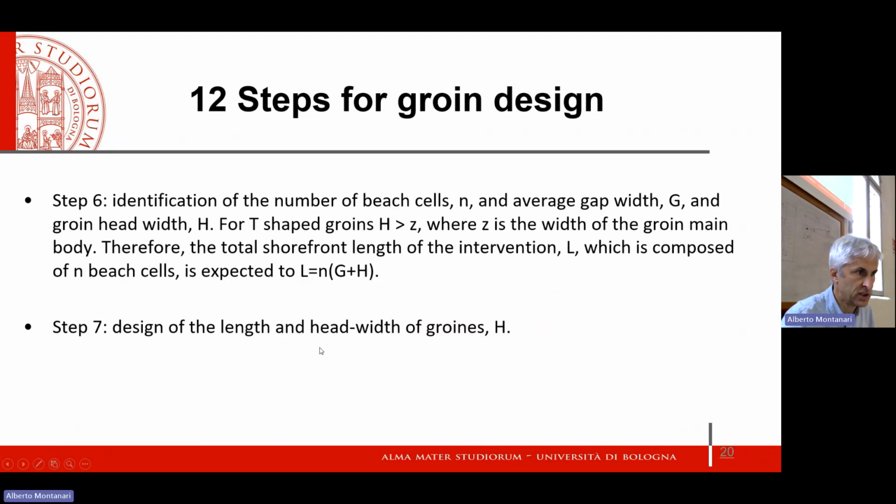Now, step 6, identification of the number of beach cells, number of groins. Let's call with the symbol lowercase n the number of cells. The number of groins is equal to the number of cells plus 1. Okay, the cells are the intergroin spaces.